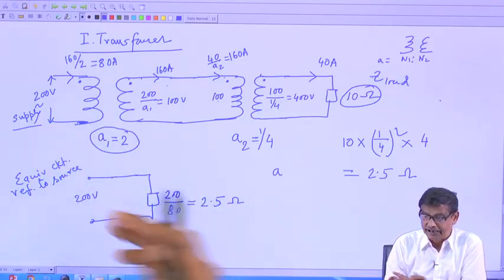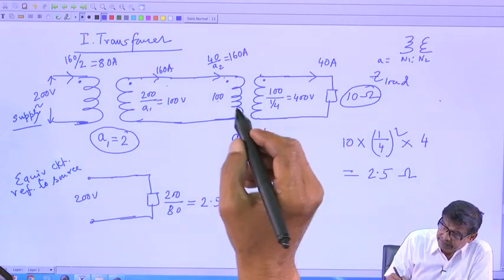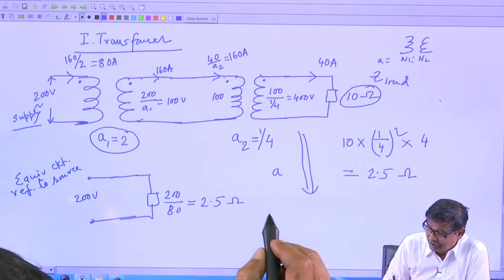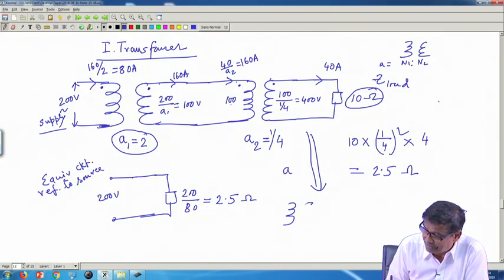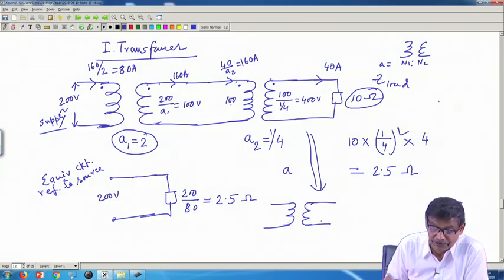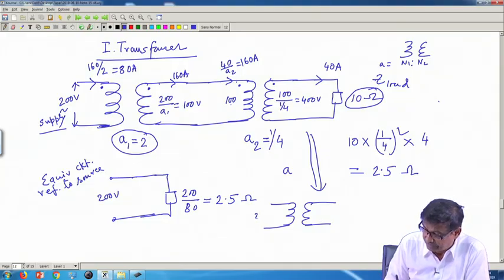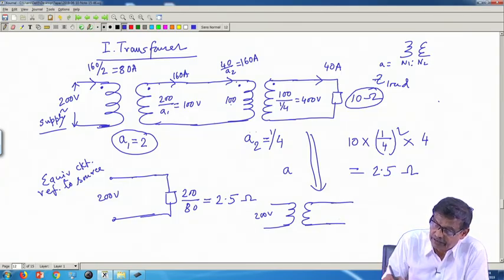So, have a lot of practice, so that you can transfer the impedance. Just to conclude this, this whole system can be drawn like this also. If I go step by step, first transformer, I am drawing this whole circuit here. This is 200 volt, fine, and here was a transformer. Treat one transformer at a time, eliminate this transformer first.